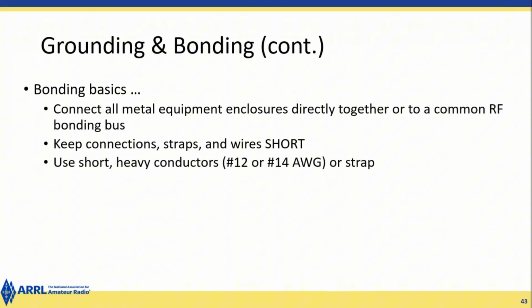Here are some causes and some solutions for RFI. Some solutions are things like RF chokes. You can put RF chokes on wires, on lines. You can put low-pass filters on transmitter outputs if you have to.